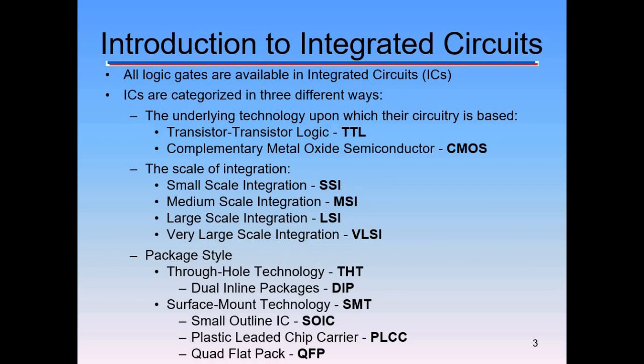Well, there's 2 major kinds of transistor logic that we go through. The chips that we use in class use TTL logic, so those are the 74LS, then whatever number we have, 08N or 08P or 32N, those sort of things. Those are called TTL logic gates, and when you use Multisim, remember that's going to be under the TTL.